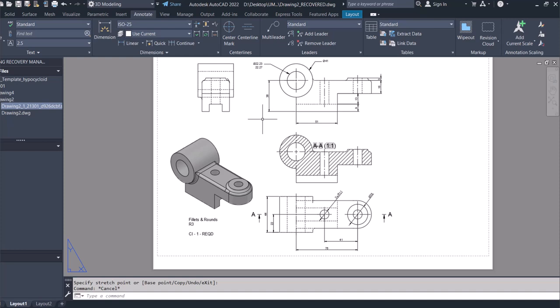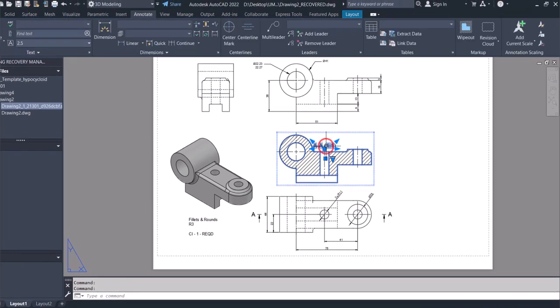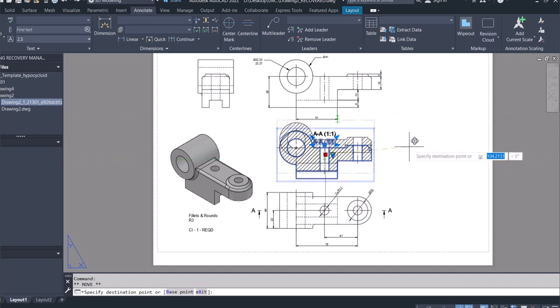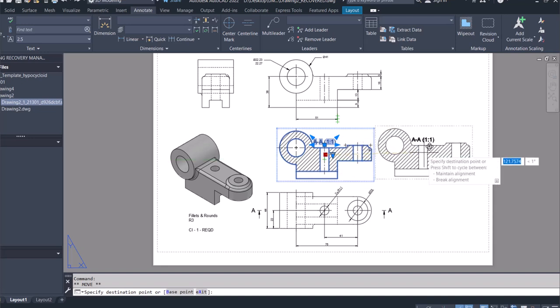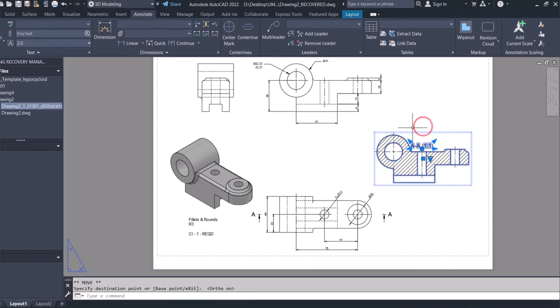Okay, and I may want to select the entire thing, the view itself with its name, and then move them. I can click on this and move to my left, I can move up and down, but not left and right. So to move to the right, I would hit shift on the keyboard, and now I can move. I'll position it somewhere, maybe here, leave it there. I hope that's far enough.